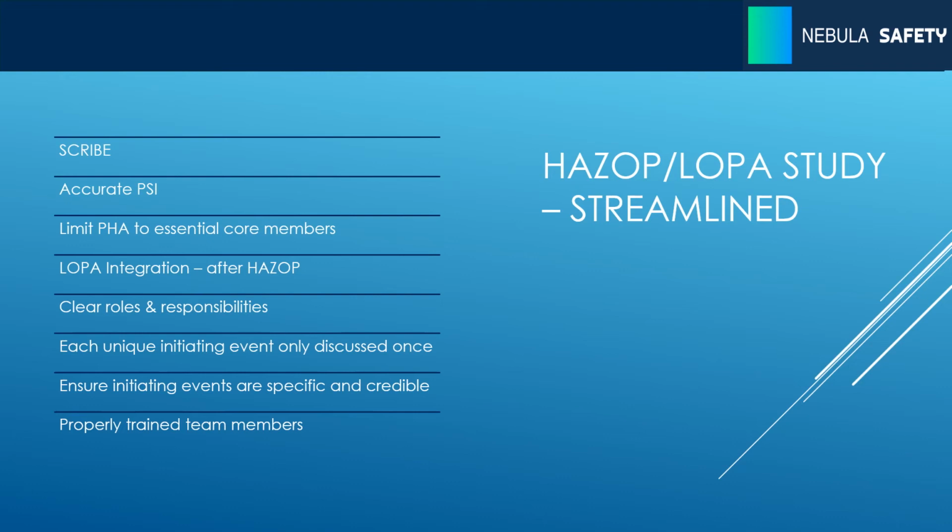present. That being said, I have worked for certain facilities that prefer to do the LOPA on a case-by-case basis. The second you come up with that high-level event, something like a fatality or an off-site impact, you'll typically do the layer of protection analysis right there and identify any additional safeguards that might be required, or use the LOPA to reinforce the team's assessment that perhaps it is not a significant risk scenario.